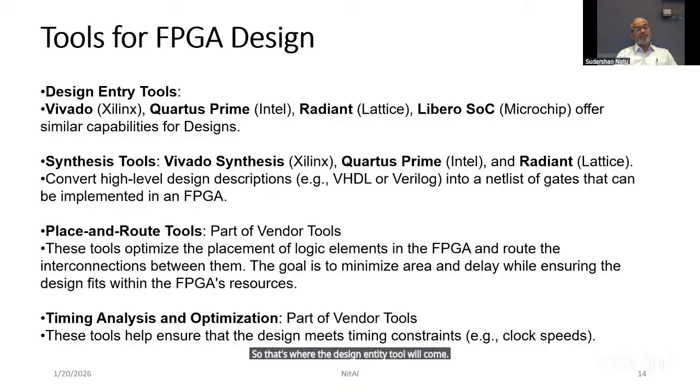The next tool comes at the synthesis level. In the entire semiconductor terminology, what we call the compilation process is typically called the synthesis process, because it's not just converting software into some kind of logical instruction, it is synthesizing your higher level language into an executable gate level physical hardware, and that's why the terminology came as synthesis. It's not a 1:1 translation, and that is the reason it is a synthesis process, and there are tools specifically for that.